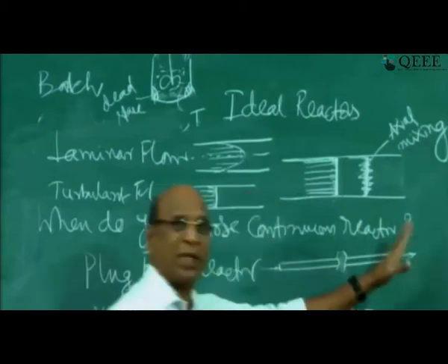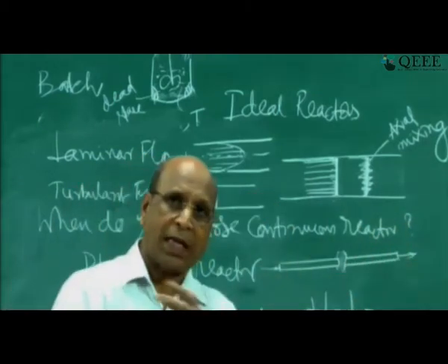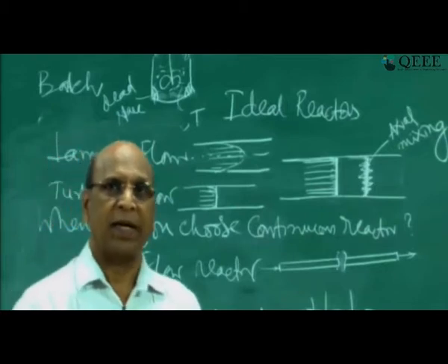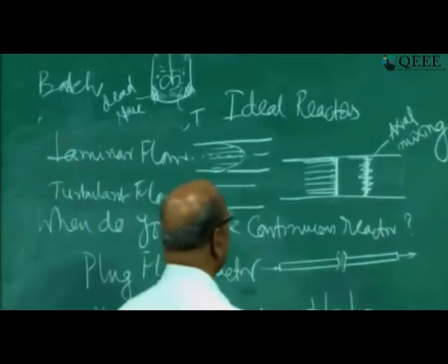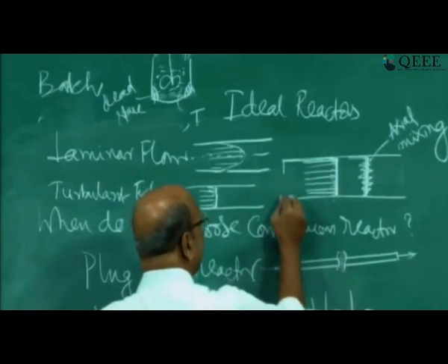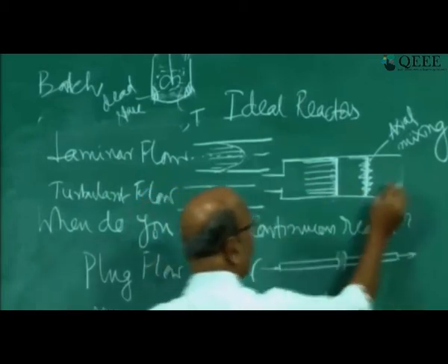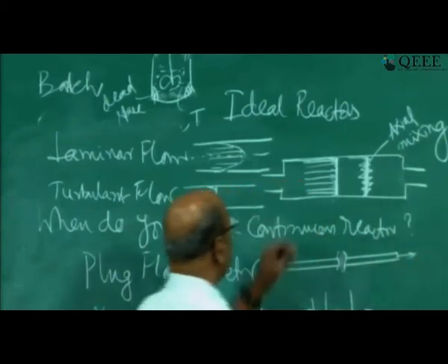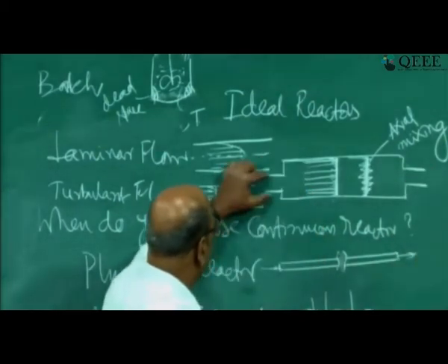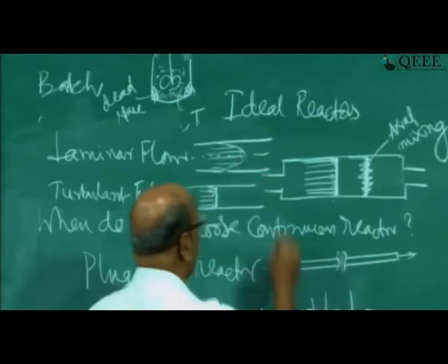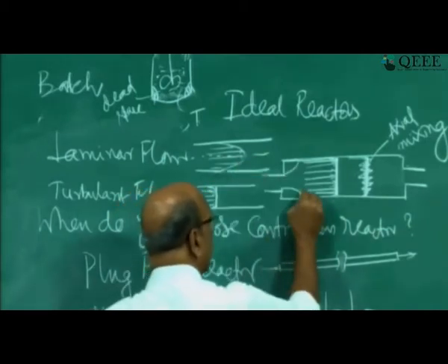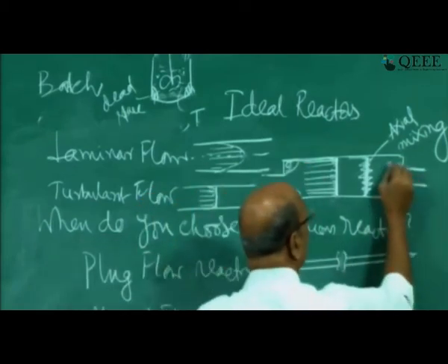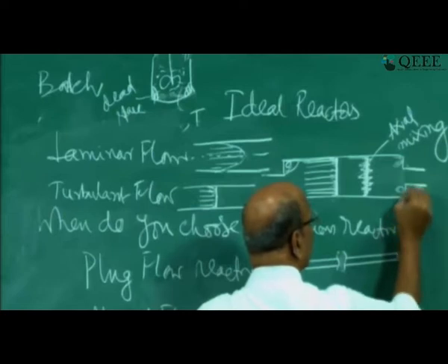Axial mixing is not allowed in the reactor. That is one thing, right? The other one is that when the material is entering, you may have the inlet and outlet something like this. If this pipe is slightly bigger, you may connect it with a smaller pipe, where now you have dead space here, and here also you have dead space.